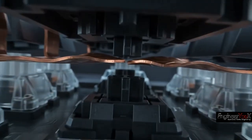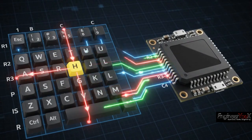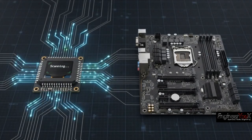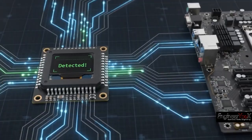When you press a key on the keyboard, the keyboard's matrix detects the exact row and column of the pressed key. The keyboard's microcontroller then identifies which key it is and looks up its corresponding scan code stored in its memory. Finally, it sends this scan code to the computer as a stream of binary data, zeros and ones.